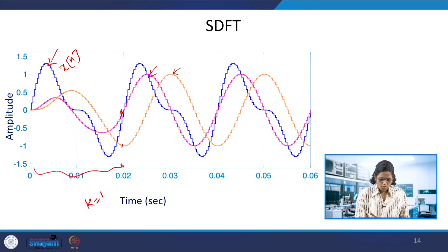So you can plot it instantaneously. After N minus 1 samples, you get the instantaneous output of the fundamental itself. You can vary this k also up to N by 2, and when we increase k, if you fix the Fs the same, then the number of samples per cycle would reduce, depending on the k that should be considered. Otherwise, there are mechanisms to increase Fs and keep the number of samples constant over all the cycles.